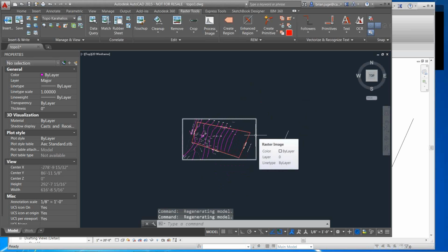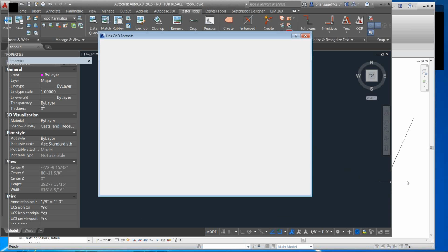But if you don't, or you're doing something like this, we need to move this CAD file within that 20-mile radius. Now, things outside of 2 miles actually get a little graphical errors, so I would recommend you be closer than 20 miles. You want to be within 2 miles, which is a pretty small area for a site plan when we're talking with the civil guys. Not that they're always that civil, but we have them in here.